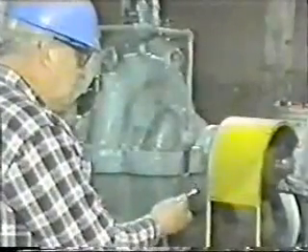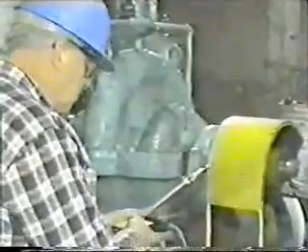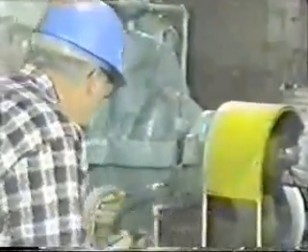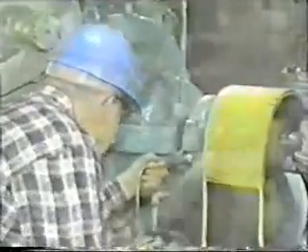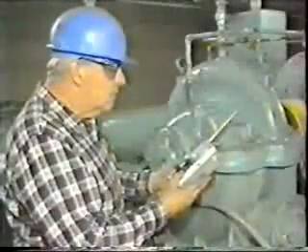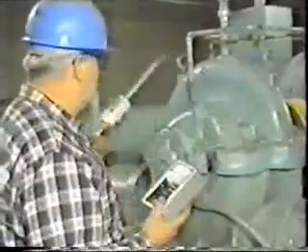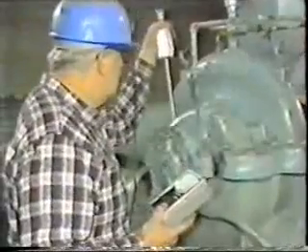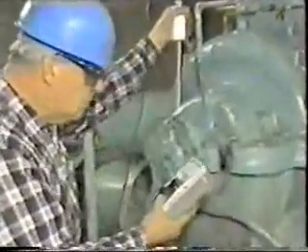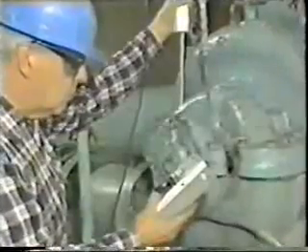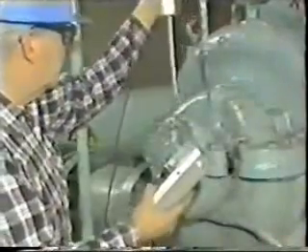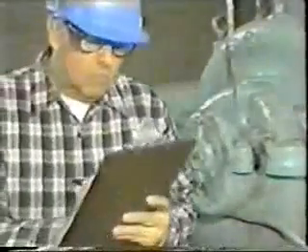You'll remember that the operator told him there was no temperature increase on the other bearings, but it's good practice to check both bearings. After finding the temperature at the other pump and motor bearings to be normal, Gene makes a check for excessive vibrations at the outboard bearing. Excessive vibrations could indicate bearing failure. When the probe is placed on top of the housing, it measures vertical vibrations. Each time he takes a reading, he records the reading. Later, he'll check these readings against the specified normal range for this pump.